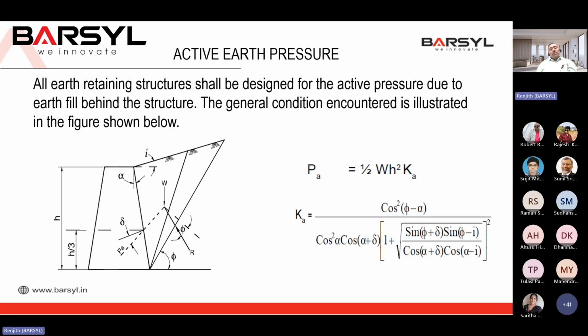The factor K equals cos squared (phi minus alpha) divided by cos squared alpha cos (alpha plus delta) into [1 plus root of sin (phi plus delta) sin (phi minus ...)]. So that is the equation. Reading that figure, we have to find out what phi, alpha and so on are, give the inputs and we will get K. Usually it is 1/3, but to be precise, for a bridge design we have to exactly calculate K. So that is the active earth pressure.